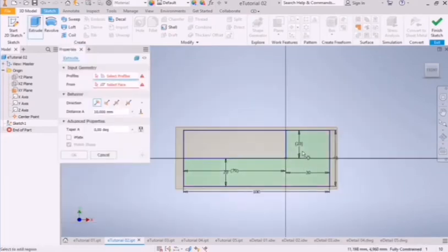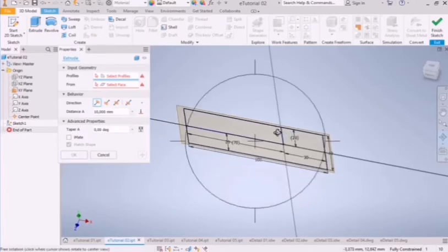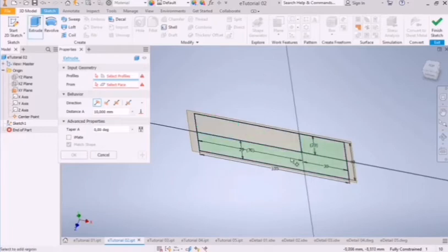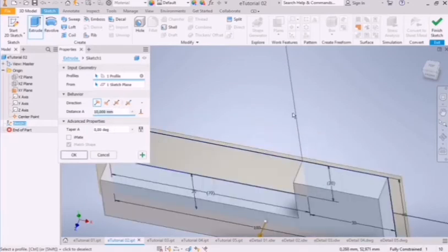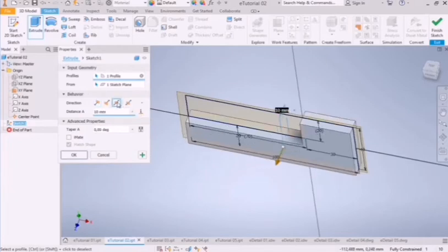Let's zoom out, and then this is the area that we need. Okay, but let's put it on 3D so that we can clearly see what we are dealing with. Right click and then say okay, then we select the area that we want to extrude. That one we don't need, and then we want to extrude it symmetrically. And then let's change the dimensions to the dimension that we want.